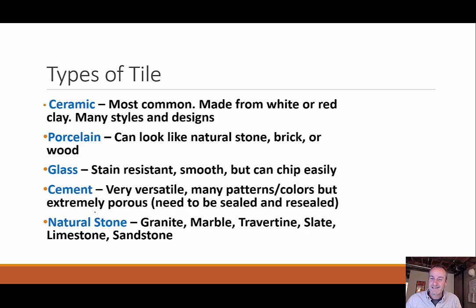Problem is that has to be done on a yearly basis or so, depending how porous the material is, and what you use as your sealant. But that's what it means by sealed and resealed. It's the same thing with natural stone. So granite, marble, travertine, slate, limestone, sandstone, those are all examples of natural stones. All of those are porous and need to be sealed.